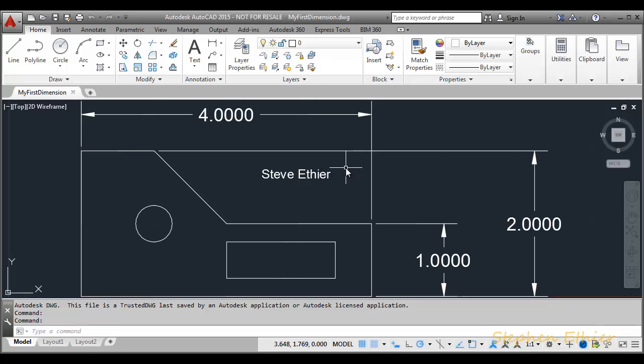When you zoom extents, anything that is visible in your drawing will be shown on the drawing screen. So if the drawing looks odd when you use zoom extents, look around the edge of the drawing to see if there's an extra object that you don't really want. When you find it, erase it, and repeat the zoom extents until your drawing looks proper in the drawing area.